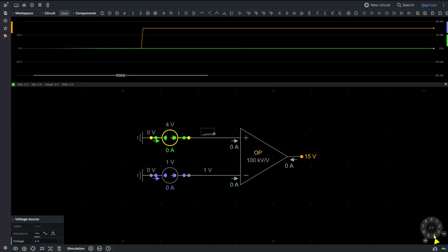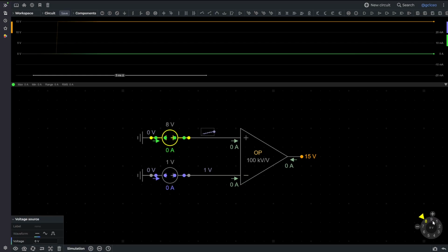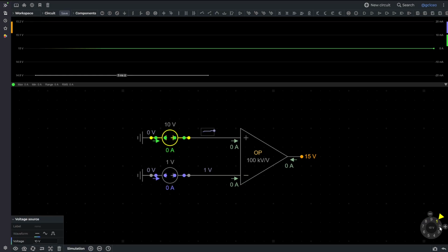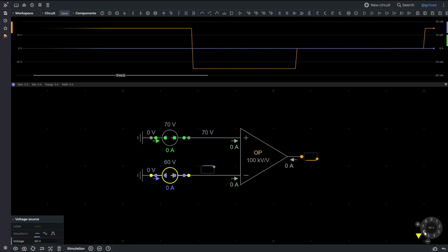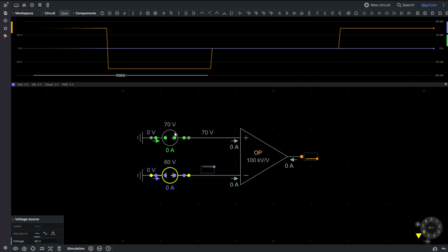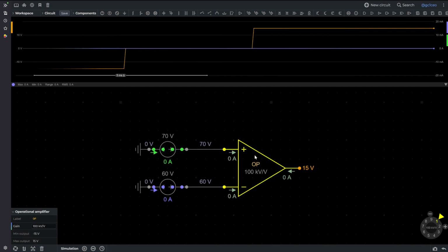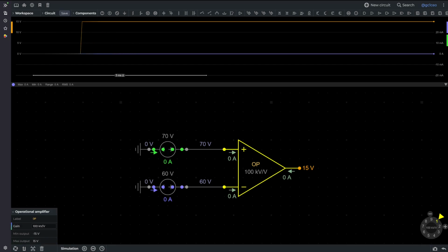And increasing that number isn't going to matter, at least it shouldn't up to the voltage rails. Now, again, this is basically perfect, so it goes rail to rail. So 20, even then it's not affecting. Let's set it to 80. Let's set it to 70. All right, and we're back to 0, 60. In real life, I believe there's problems once you hit the minimums and maximums there.